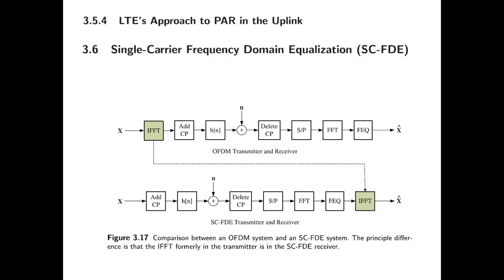Okay, so what is the proposal here in LTE, that is 4G, for a transmitter at the downlink, that is from tower to the phone? They suggest an OFDM based system, which contains an IFFT at the transmitter, that is at the tower, and an FFT at the receiver. Whereas you can see the SC-FDE block is something similar but much different.